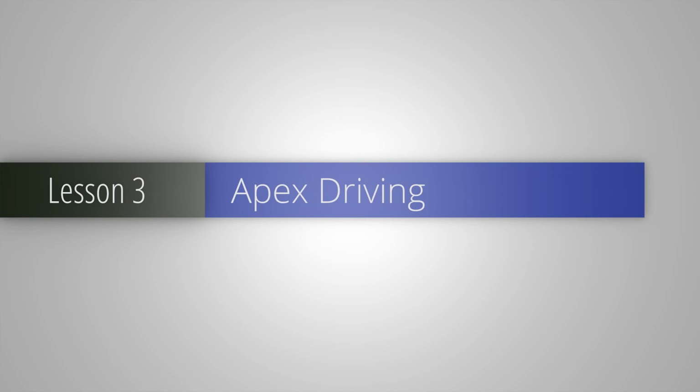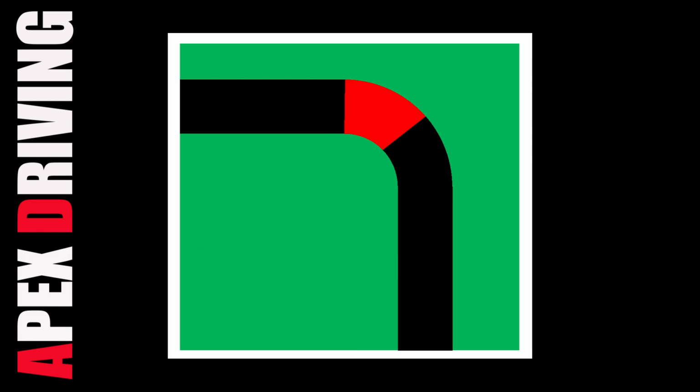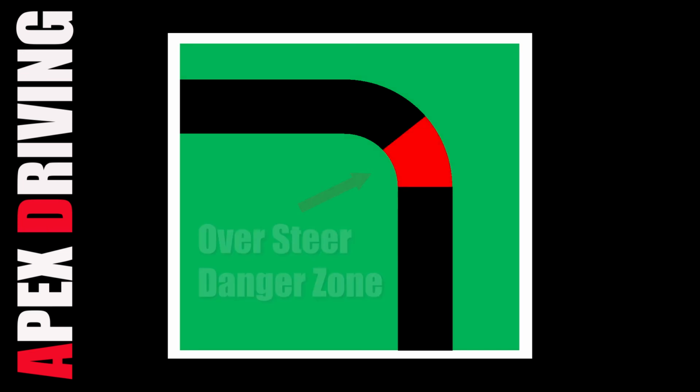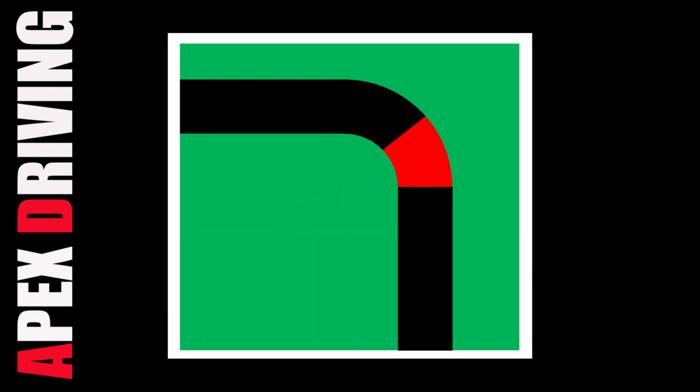Last lesson of this video, apex driving. Now coming into a corner is always the danger zone for understeer, while coming out of the corner is the danger zone for oversteer. Basically where these two zones meet is the middle of the corner, and that is called the apex of the corner.